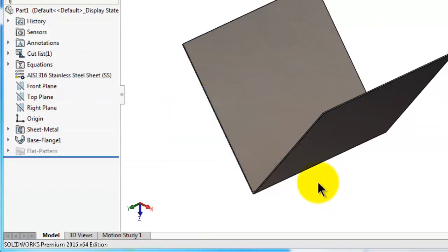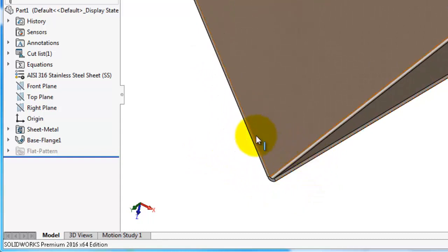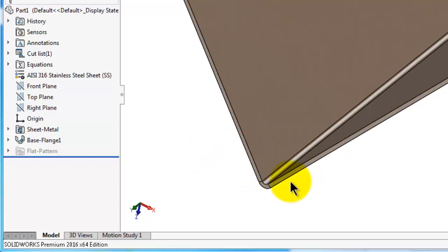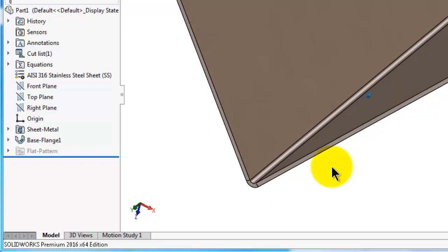Why is there a bend allowance? The reason for that is there are different materials, and as we said, when you bend a sheet of aluminum, it will not give you the same dimension as bending a sheet of steel, and so on with copper. Also, the type of press you are using. If you have a press with a bigger bending radius, that will also affect, for example, the K factor.